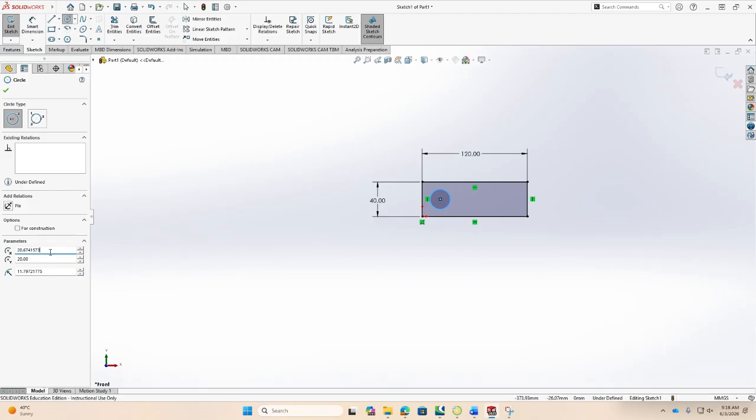That's again a rule of thumb, not a definite guide, but it's a general practice to avoid unnecessary stress concentrations around the edges. So here 1.5 times the diameter of 12 is 18. So 18 plus 6 will be 24, right? So the center of the hole will be 24 from the origin along the x-axis. So that's how I will do that.